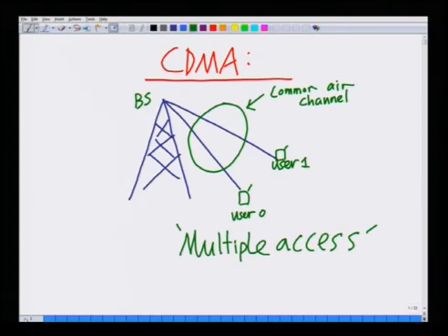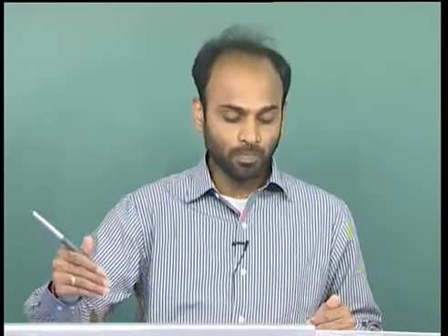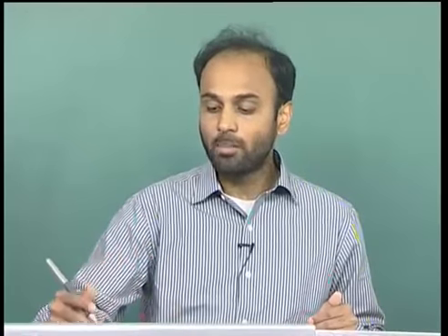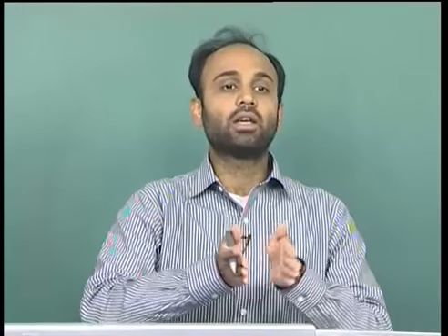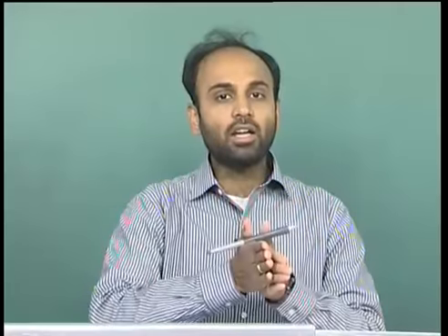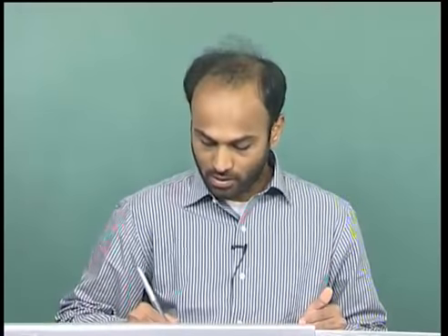Now, why is this a superior technology? We are going to see the reason for CDMA being a superior technology as we go through this lecture and the next couple of lectures. A multiple access technology is at the heart of every cellular technology, because every cellular technology implies that this common air channel has to be used to transmit multiple information signals to different users. Hence, I need a multiple access technology. There are several multiple access technologies, and CDMA is a more sophisticated one. So, let us start our discussion of CDMA.